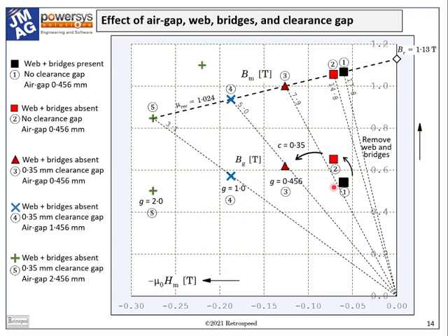Here we are not wasting 20% of the magnet by back leakage through the web and the bridges, but we don't get a 20% benefit because we've had to increase the air gap to make room for the carbon sleeve or Kevlar banding. This is the crux of the whole business.